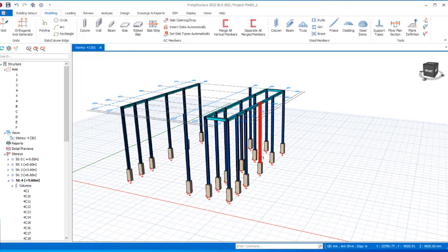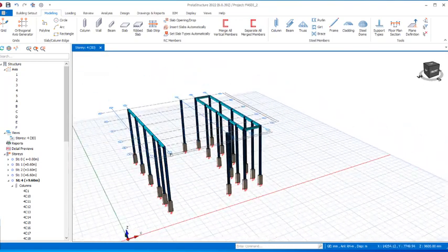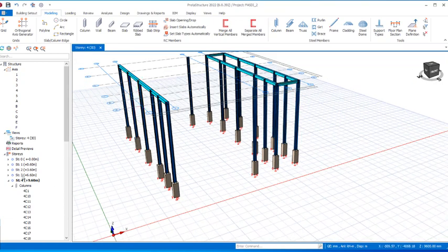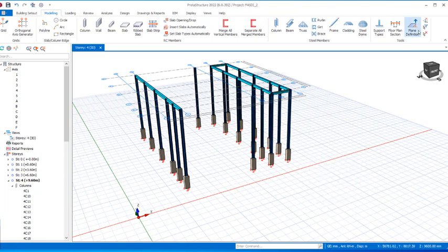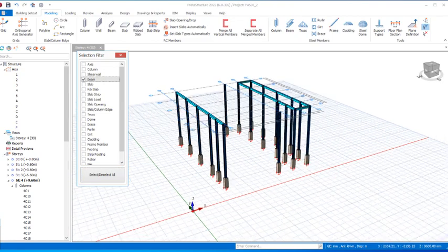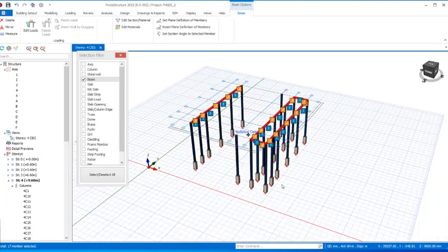All right, so after having done that, choose all, make sure all is selected in the selections filters, and then close this dialog. All right, so after having done this, we want to be moving these beams, we move the beams from first floor to the third floor, and as well to the second floor. Okay, so we still do the same thing, filter this, okay, to only beams. So deselect all, select only beams. All right, at this time you can select only the beams, just like this, after which you just have to